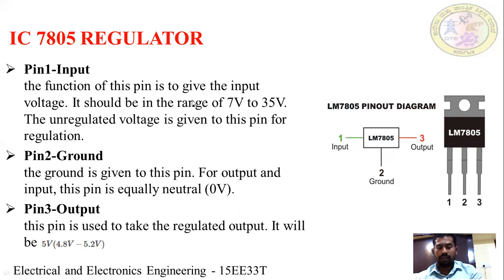First we go for pin number 1, which is given for input. Pin number 1 is mainly there to provide the input voltage. It should be in the range of 7 volts to 35 volts.